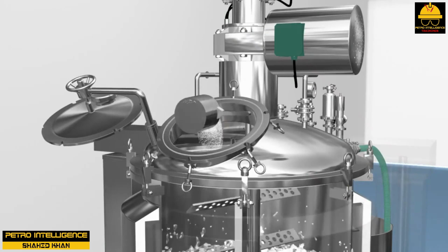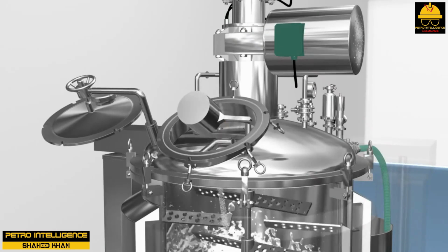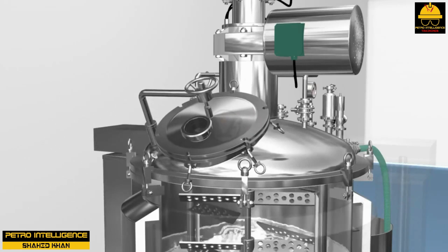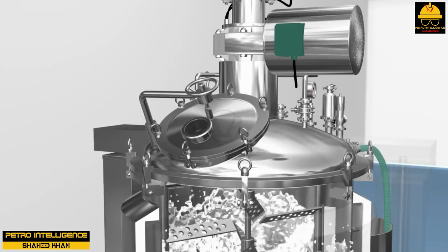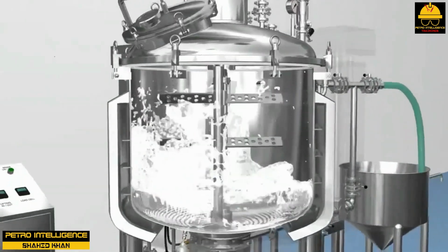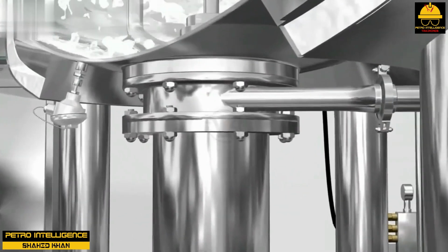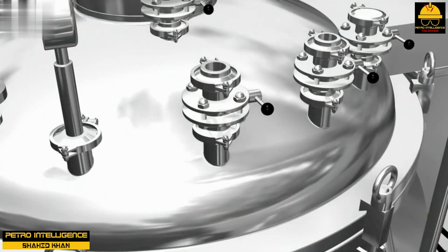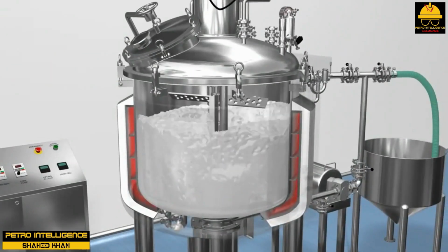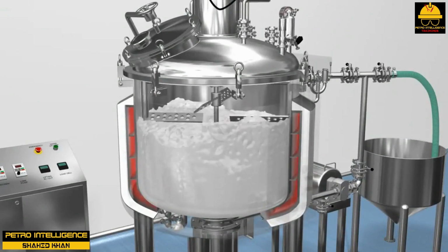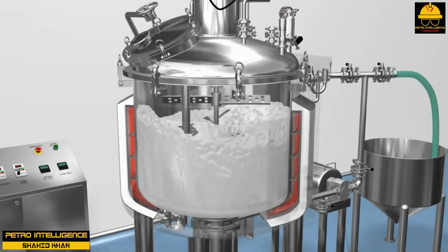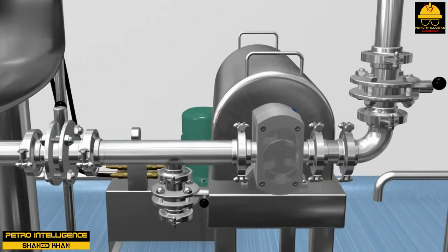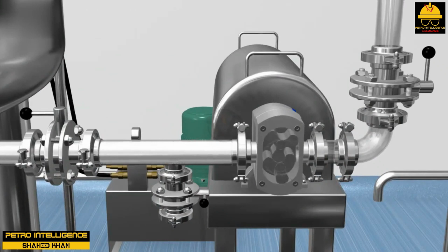Stirred tank reactors are used for liquid-liquid reactions, gas-liquid reactions, and liquid-solid reactions. Stirred tank reactors are used for reactions that require a relatively long reaction time and for reactions of slurry or thick liquid in which mechanical agitation must be used to provide a uniform reaction mixture. Such reactors are also used when the production rate is to be variable, and several different reactions or products are to be made in the same reactor. The early research and development of most processes is conducted in batch stirred reactors because of their versatility.